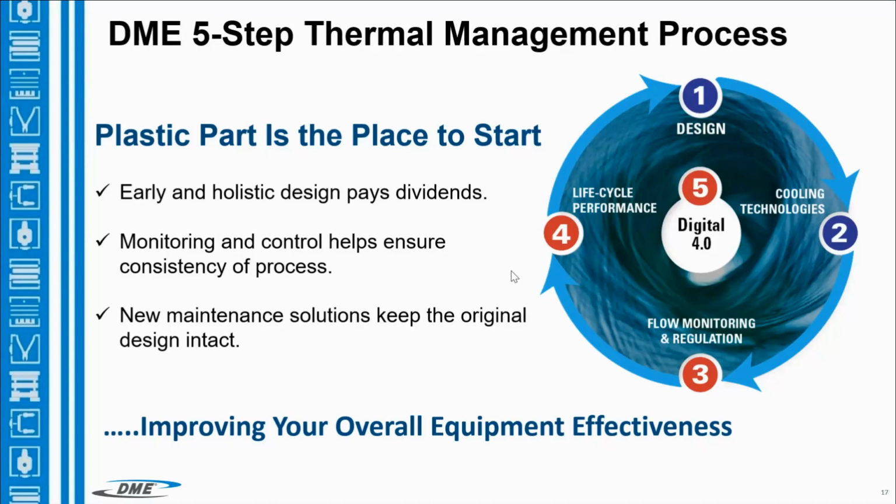Implementation of a cooling technology monitoring system at each molding machine. Go to your shop floor and ask your process technicians or engineers or your quality engineers and see how many times they've run into a molding machine that had the water kick off and they continue to run parts.